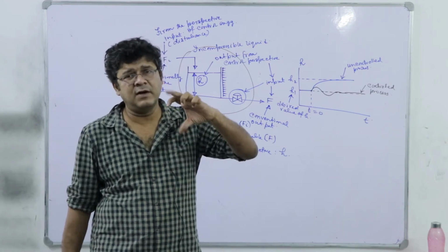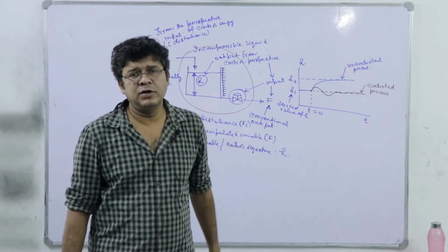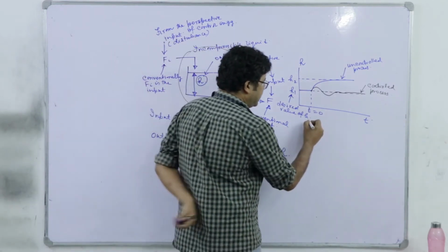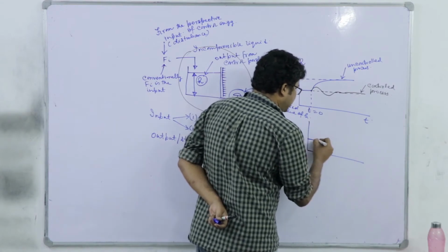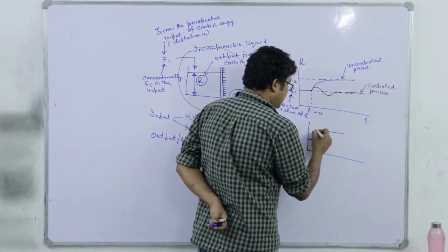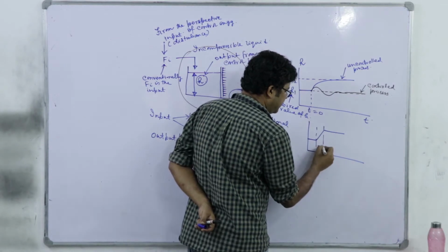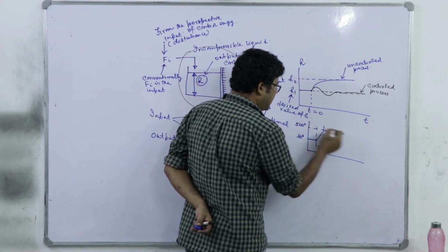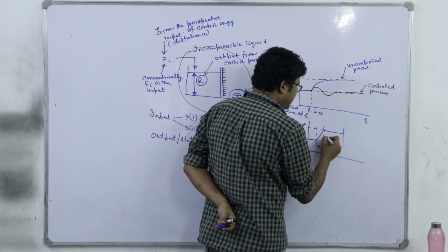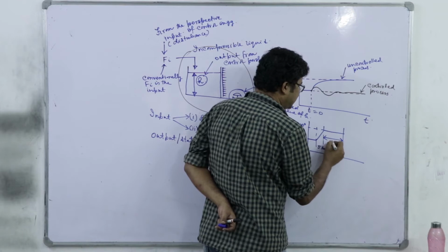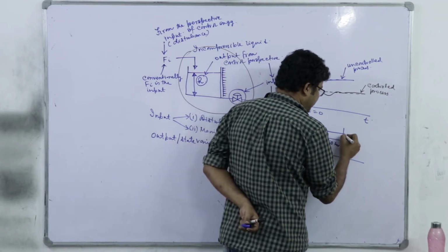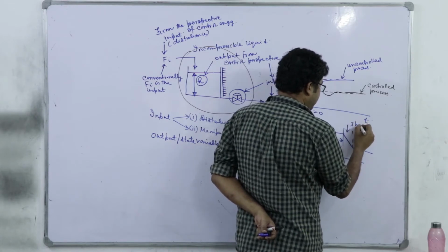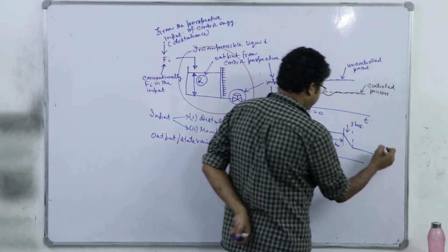So the required temperature profile is something like this. Over these 5 hours, from 30 degree to 500 degree, and here it needs to stay for another 10 hours maybe, and again the temperature must drop linearly over another 3 hours, again to 30 degree.